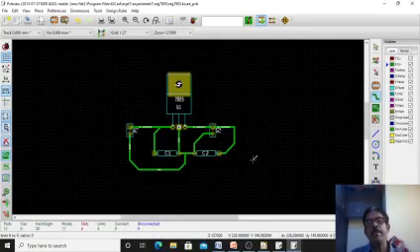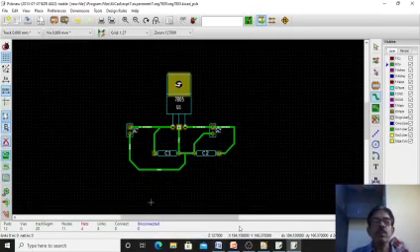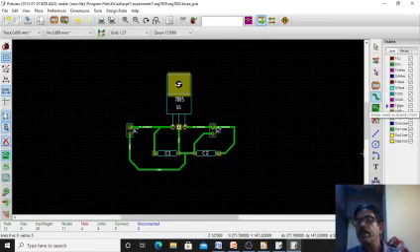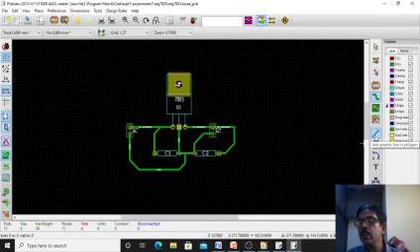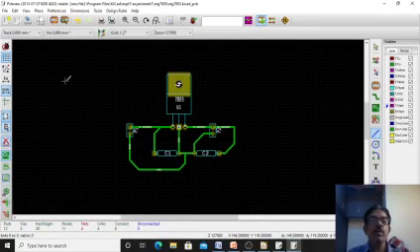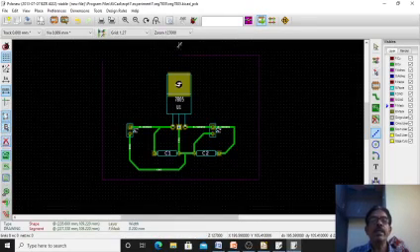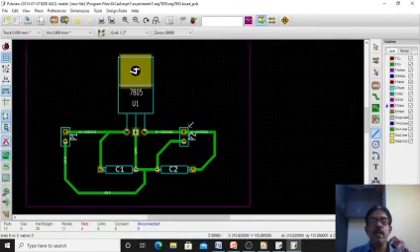Now PCB layout is ready, right? So you can put the boundary on this. Okay, so for putting the boundary, already if you see here on the right hand side, back side copper is there. You select any front side. For example I will select F mask. Then for putting the boundary I will select this add graphics. Then on this I will be selecting the boundary. For example click it, it will be coming like this. Then click it, turn it, click it, turn it, click it, turn it, click it, turn it. So this will be the boundary I have marked.